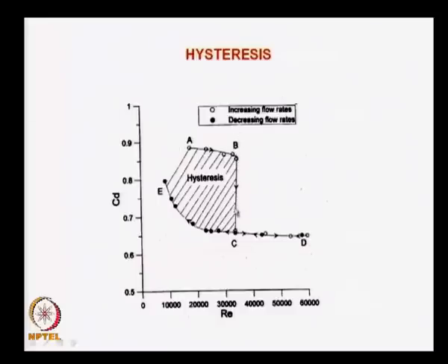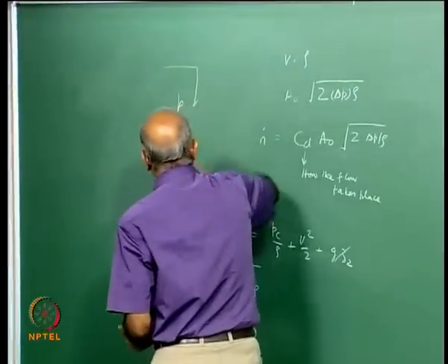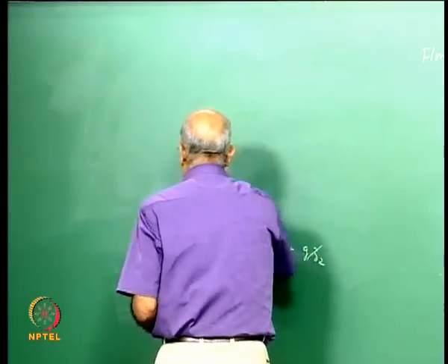Somewhere cavitation starts, it begins to separate, I go over here, it is still separated, and now when I start reducing the pressure or reducing the velocity again, it goes like this, but the memory of the separated flow lingers on and CD decreases, it never comes back to this. That means even a small thing like a shower head injector, which is nothing but an orifice like this, is not that straightforward, and what happens, let's try to put this down.